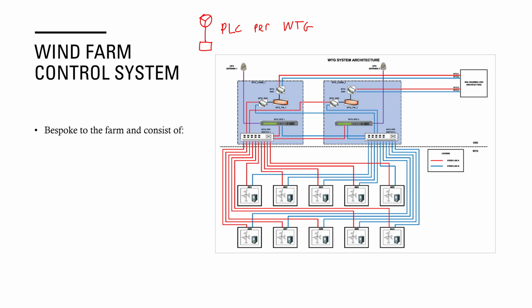In the event that it needs to open the supply breaker for that turbine, it's also capable of sending a signal into that supply breaker to do that. Generally though, that PLC in that turbine is concerned with that turbine and maximising the power output of that turbine. There is a high voltage control system. This is the highest integrity control system on the farm, and this is the only system which is allowed to close HV breakers.